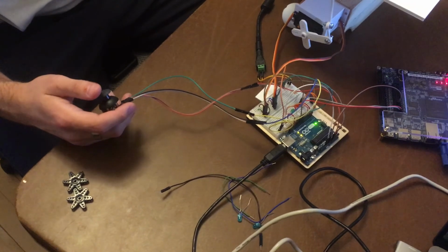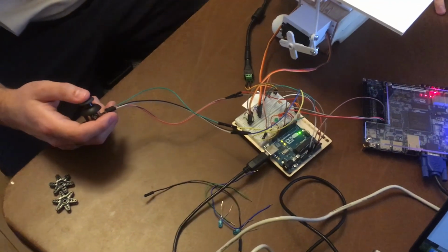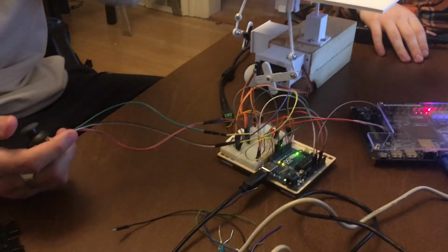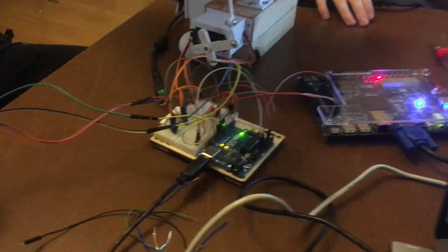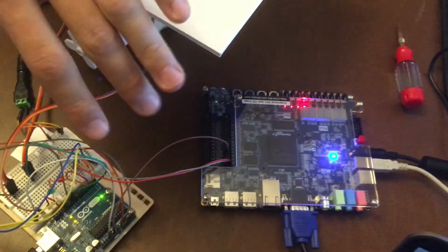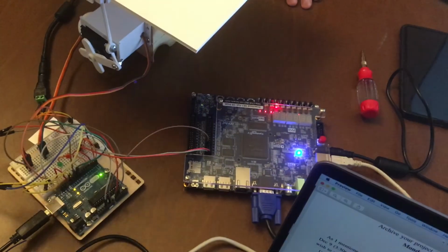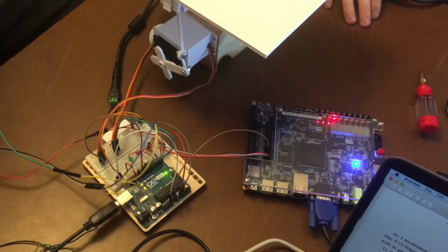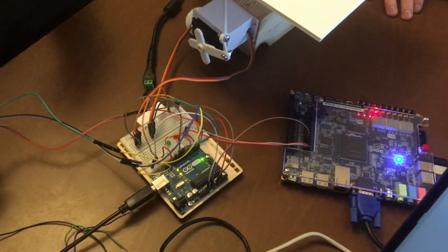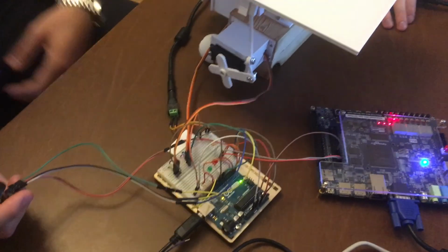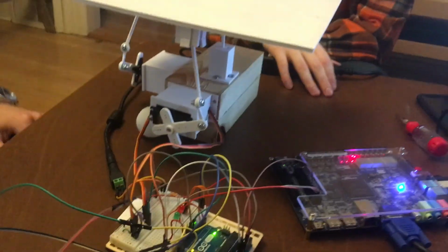Got our final project built here. We got it working. So this is the joystick controlling the board here. The joystick inputs are going into the Arduino, where we send it serially to the FPGA. We have a UART module in there that receives the data, and our CPU processes and maps those coordinates from the joystick and then sends it back through our UART to the Arduino, where the Arduino writes to the servo motors and moves it.